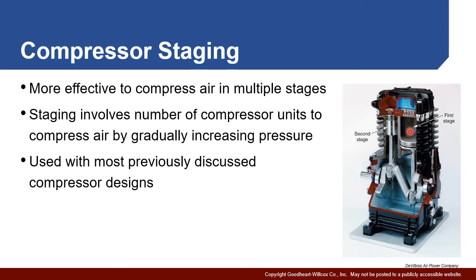The idea is this is low pressure, and as a result, it's high volume. As the pressure goes up, the volume goes down. So to continue this operation, you need a smaller piston here. The other issue from a mechanical standpoint, we want the force being generated by these two pistons to be pretty close to the same to balance out the system. So in this case here, we have low pressure and a big area. In this case, we have high pressure and a small area. And what we're trying to do is keep the forces pretty similar in terms of their overall amount pressing on the system.